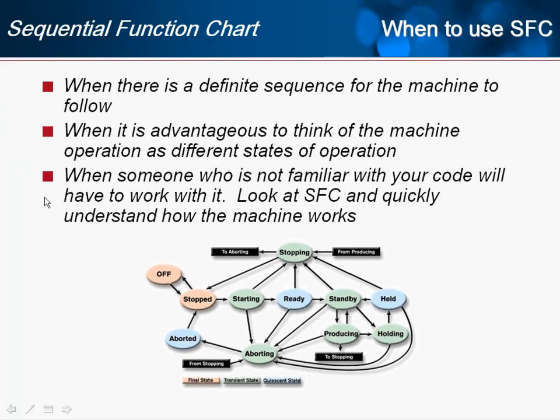And then thirdly, when to use SFC, think about the future. Who might need to work with the code that you're writing? Maybe it's a technician that has to diagnose a problem in the machine, like we mentioned before. There's a failed part of the machine, or etc. Or maybe there's going to be an improvement or upgrade to the machine program.